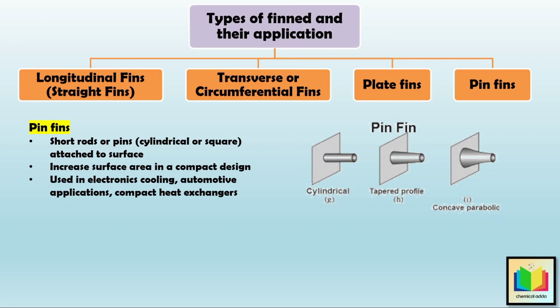So in short, in longitudinal fins, flow is parallel to the tube axis, used in double pipe exchangers, for gases, viscous liquids, and low heat transfer coefficient fluids. Then in transverse fins, flow is across the tube, used in cross-flow exchangers, like economizers and condensers. Then in plate fins, thin plates are mounted on tubes, used in compact exchangers like refrigeration and aerospace. And in pin fins, short rods are used to increase area, used in electronics cooling and compact heat exchangers.